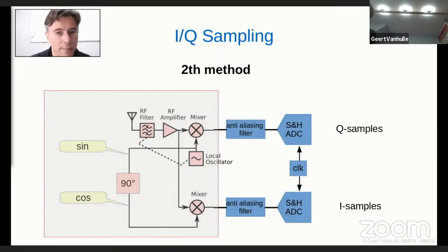We have to take care of propagation delay, all these kinds of things. Our 90-degree shift needs to be accurate. If we have a 1 degree error there, it means that our resulting samples will be incorrect in phase and not actually the correct samples to work with. So all processing done digitally later will have this error margin.